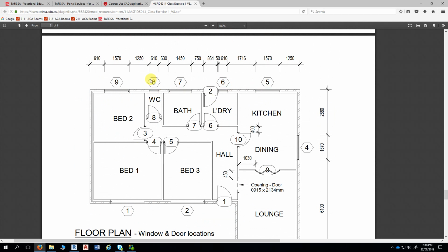And the idea is that once you've put them into the walls in the approximate positions, you then create another set of dimensions from the outside wall on the left-hand side to the edge of each window and door. So you do the same as you do with your walls, and then you can adjust them yourself, so it doesn't matter if they're not exact.